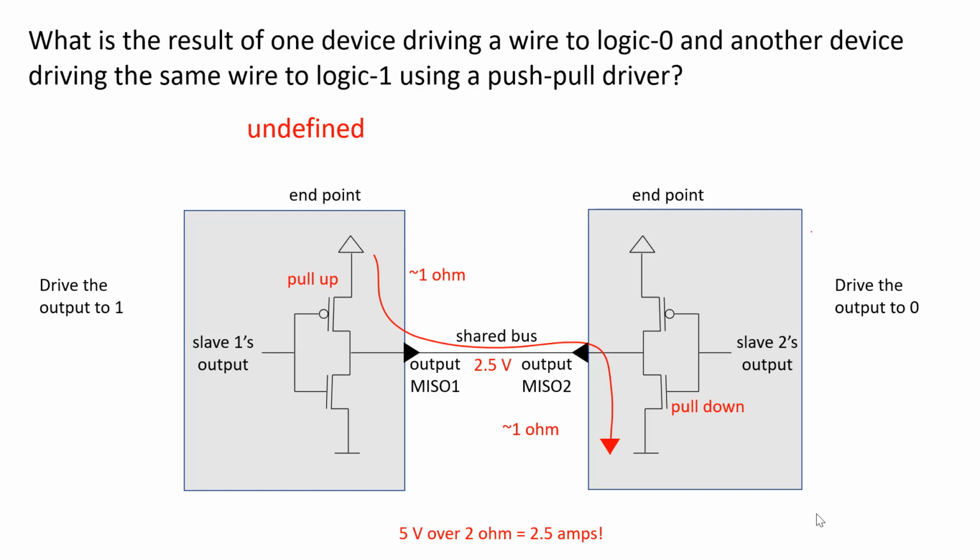You might say, wait a minute, does that mean that you can't do open drain in Verilog? You can, but to do that you have to take advantage of the Z value in Verilog, which I haven't talked about yet, but there's a special way to handle that in Verilog where you can set a wire to be high impedance Z. But if you're just setting wires to 0 or 1 and you set one to 0 and one to 1, you end up with the same problem you do with SPI, for instance, when you have contention.